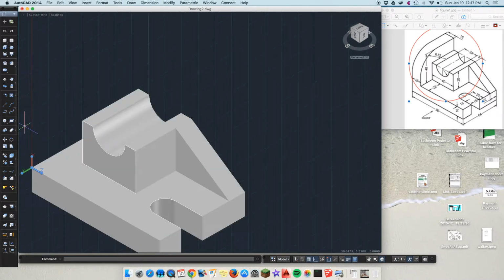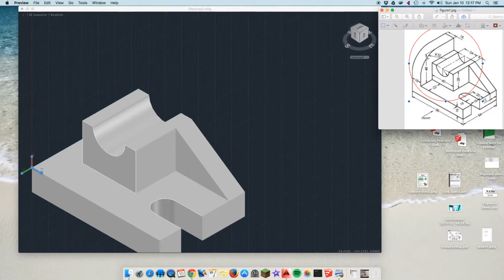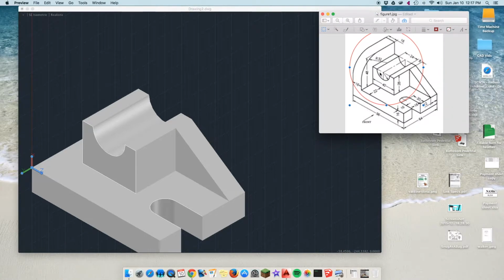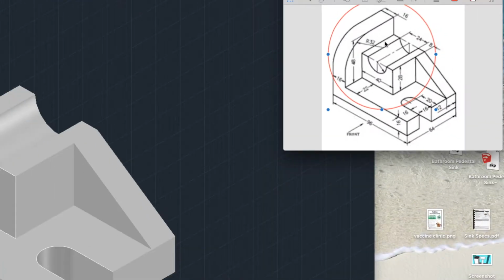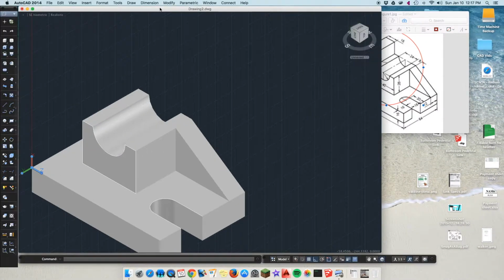If I look at it, it is 48 inches tall, and because it's the whole width of the block, it's 64 inches. So I'm going to do it by dimensions. Okay, so I'm going to do a rectangle by dimensions, and then I'll pull it back. So I'll do drafting tools, rectangle. I'll start the corner of my rectangle here on the edge where X, Y, and Z are all meeting.